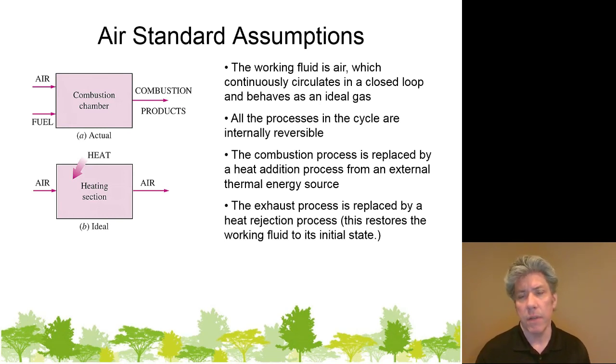Now, instead of having that process occur, we're going to assume that the air remains in the cylinder. There's no opening and closing of any valves. And instead, thermal energy is simply extracted from the air by heat. So heat flows out of the air and out of the system. So basically, the combustion and the exhaust processes are replaced by a heat addition and a heat rejection process, respectively.